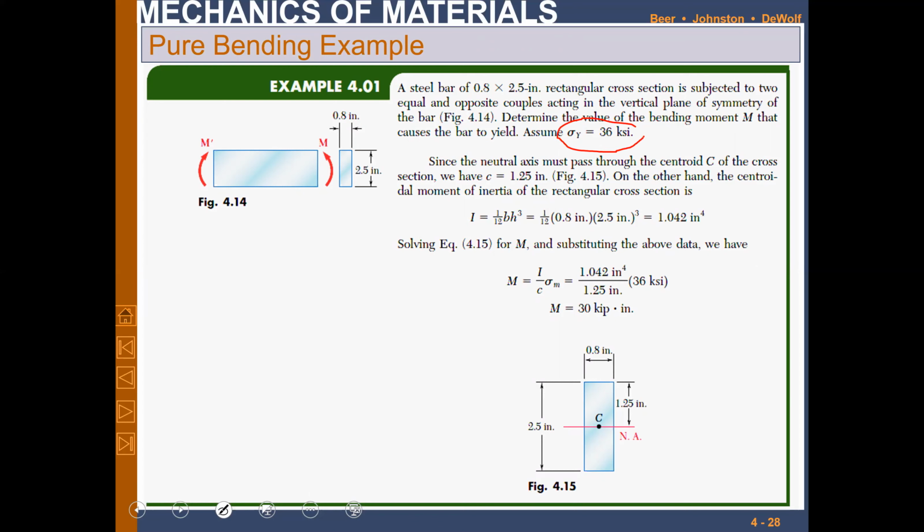Obviously we never want the stresses to go beyond this yield point. We have already discussed many times that the yielding point is the point of failure, right? So we don't want any stresses, meaning the final state of stress, all the normal stresses as well as all the shearing stresses, to be greater than the yield strength, normal yield strength or shearing yield strength, right?